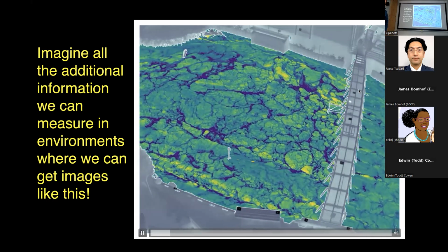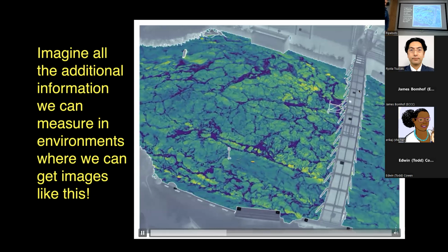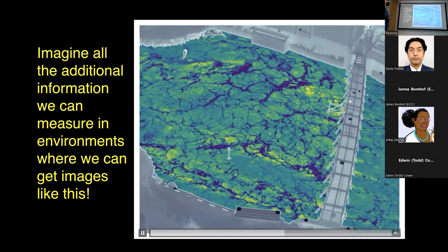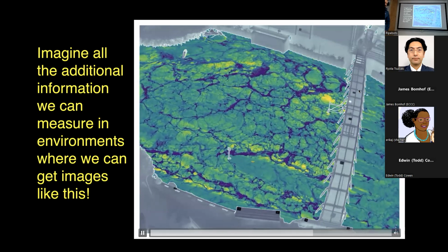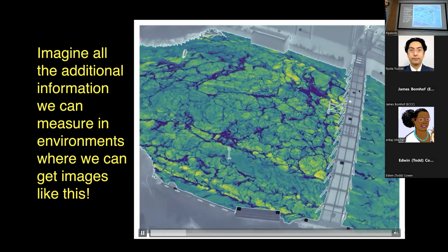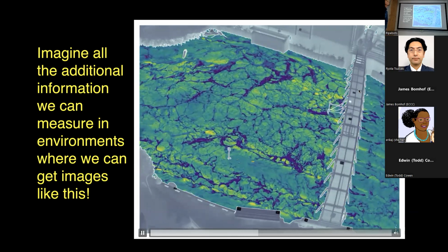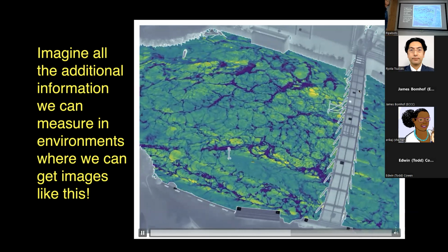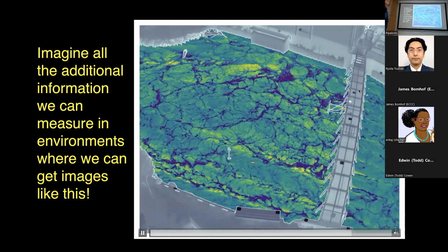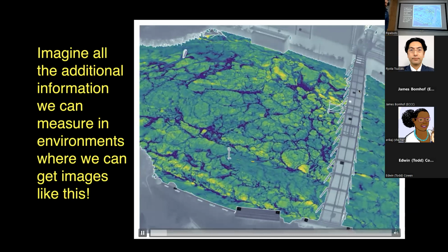And of course, in steeper gradient mountain rivers, or high flood flow through bridges and places where we have these strong transitions in the free surface, we get a tremendous amount of air. And I think it's an open question about what we can do. Like any numerical technique, the danger of our techniques is they will always measure something. Stuff is moving, right? We can see gradients in the aerated flow coming around the boulders and these very turbulent, highly unstable surface events. So we'll track something. What does it actually mean? I think that's the question in my mind.